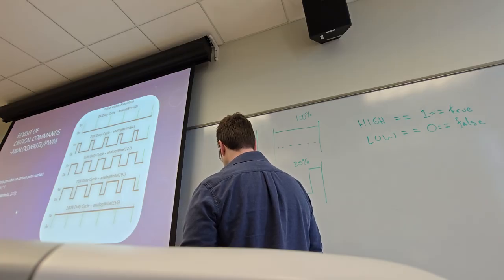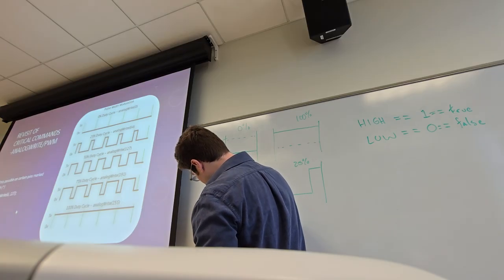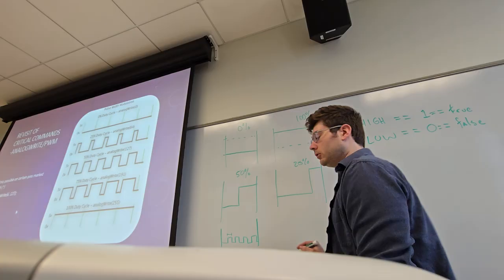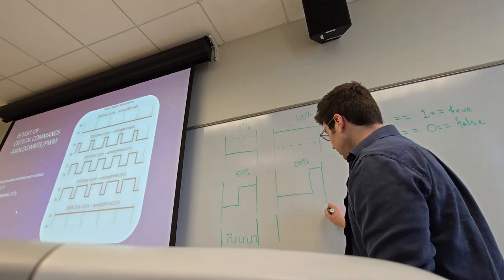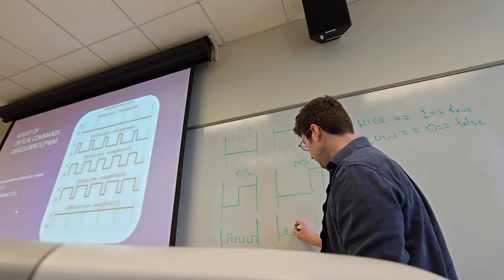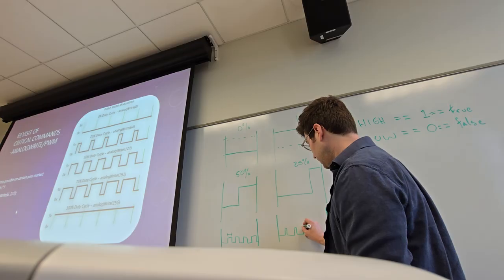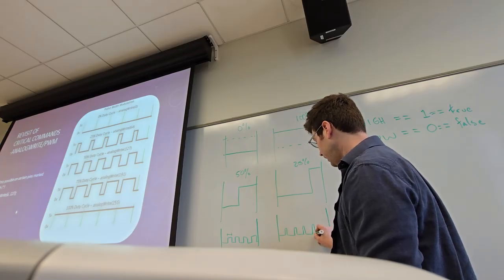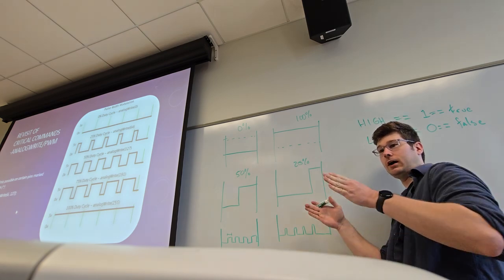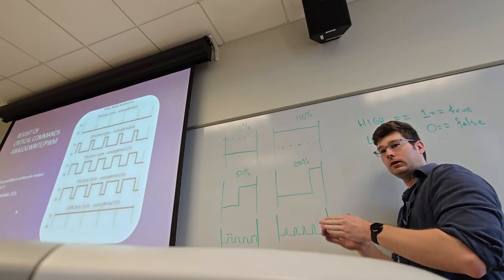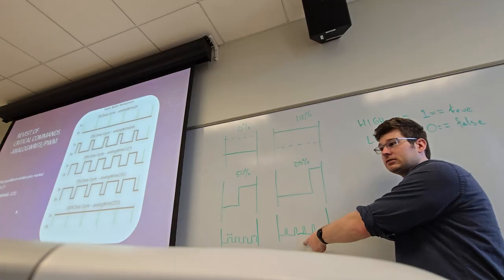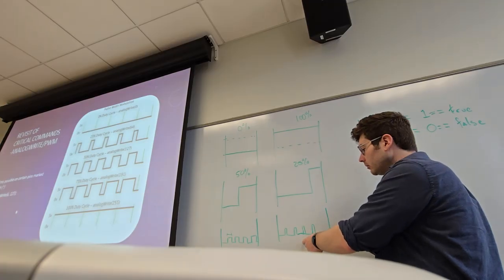Okay, so you can think of it like a wave or a square of this thickness that plays every so often, over and over. A lesser duty cycle will have a thinner blip. It'll still occur at the same time, it'll just stay on for less time. Do you see how this is a smaller duty cycle and we're just shifting how far apart the wave is? This pattern actually happens tens of thousands of times per second, tens of kilohertz.